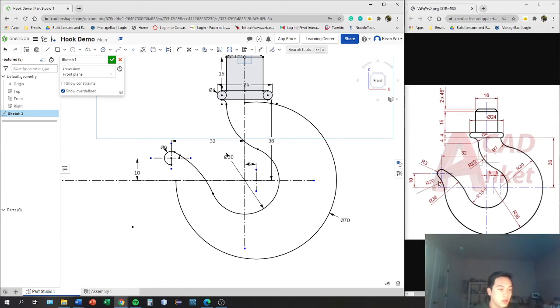And then what I'm going to do next is finish this R20 off to connect the tip part. So again, circle, C, and then tangent it. I forgot to mention, but this should be 40 inches in diameter.